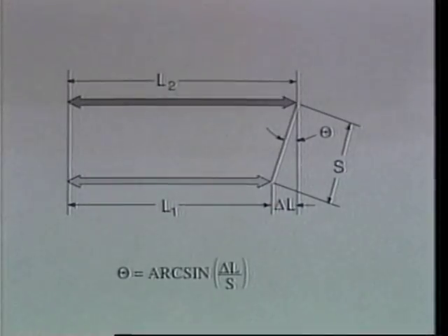From this velocity difference, there will be a difference in the Doppler shifted components from which the difference in the length changes can be determined. With a knowledge of the difference in length changes and the retroreflector separation, the angular orientation of the angular reflector can then be determined.